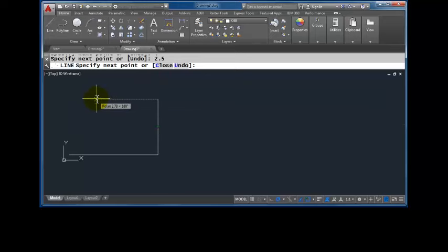Heading across the top of the front view, I have two choices. I can either enter the length of this edge, or if I hover over the endpoint of the bottom edge but don't click, and instead track up, where those two tracking lines intersect, I can click and know that that length will match the bottom edge.